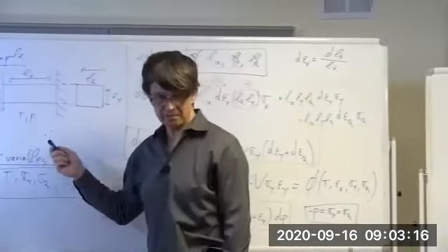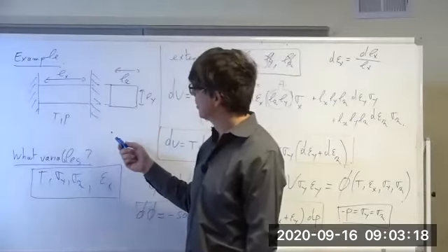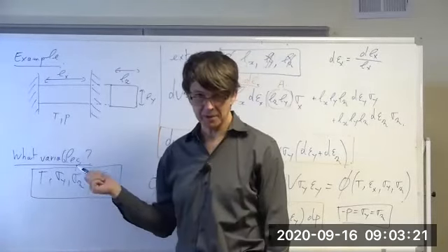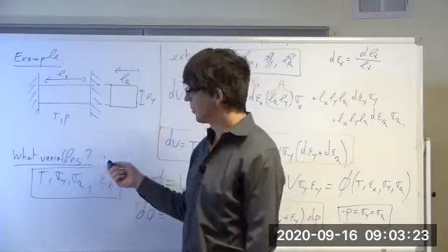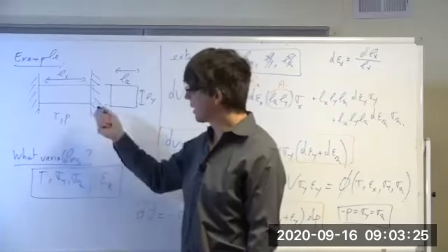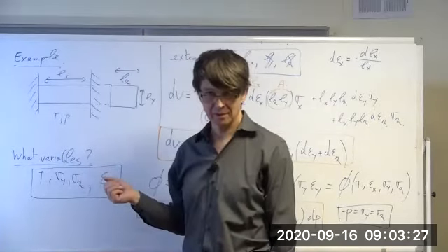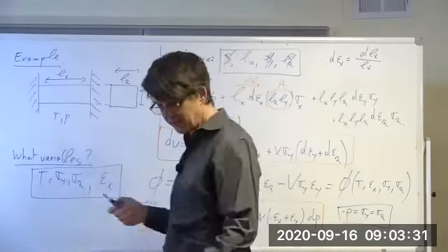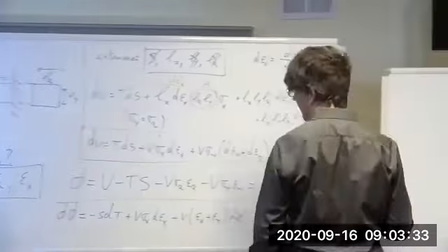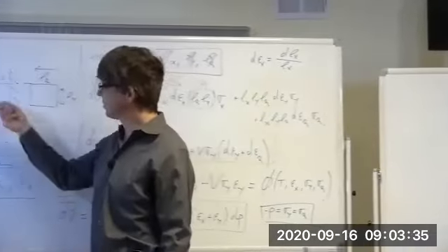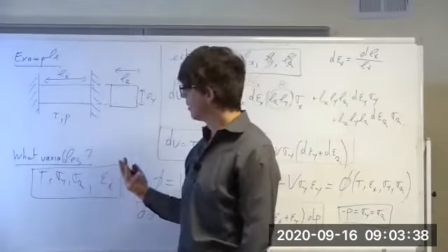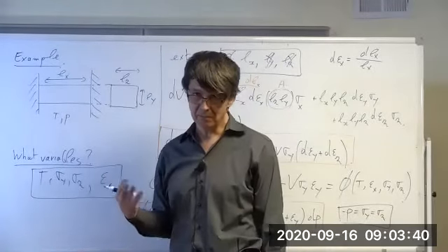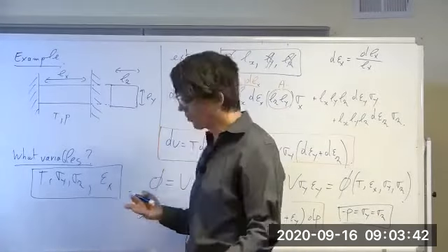So let's say your advisor asks you, what's the relevant heat capacity here? I want to try to raise the temperature of this thing, so I kind of need to know what heat to put in. If this is a block of aluminum or something, you're only going to find Cp, maybe Cv in the literature, but probably only Cp.